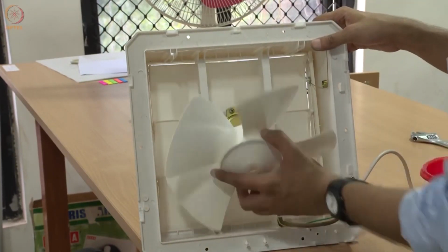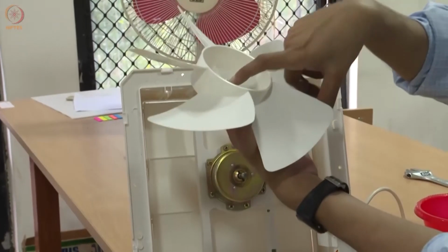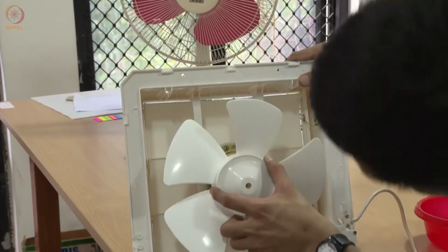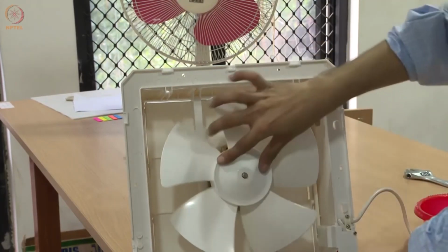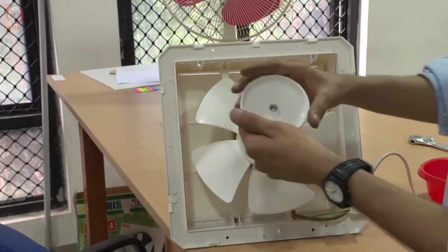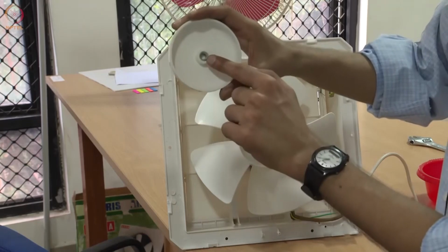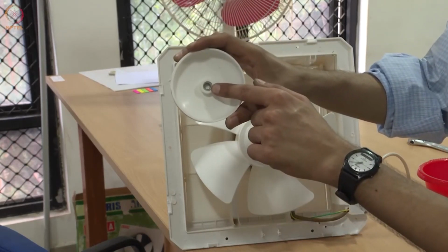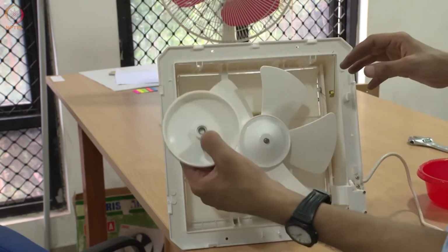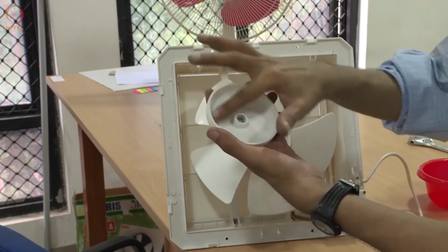And most important, please remember I spoke about the V-shaped design here that allows the blade to self-locate. All I have to do is just mount it, and then it self-aligns itself. Then you have the front portion of the fan assembly, and you can see there is an embedded fastener within it. This embedded fastener is called an insert. During molding, they take a standard fastener, keep it in the mold, and then inject the molten plastic around it.